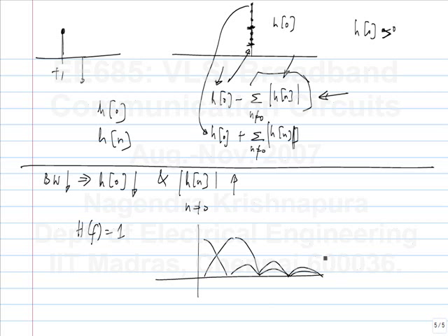It's actually easy to see it in the time domain. In the time domain, you have a rect like this, and then you sample this every Ts. So you get only a single one and all the others to be zeros. So you get the ideal value. So it's not p of f times h of f, but the aliased function of that. As the bandwidth keeps on increasing, it does get better, because it won't disturb the shape of the sinc. So in this case, h of f is 1 for all frequencies, so I can think of it as these things are getting added.